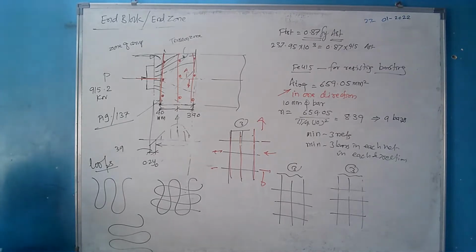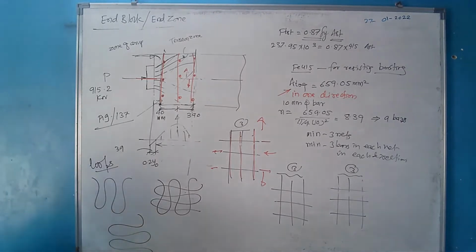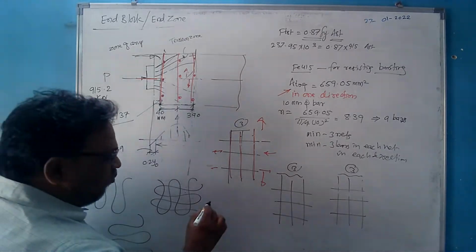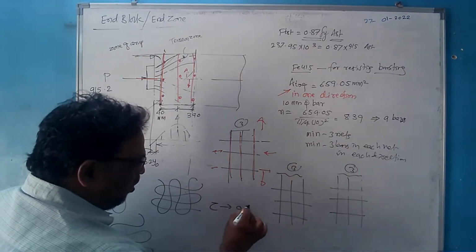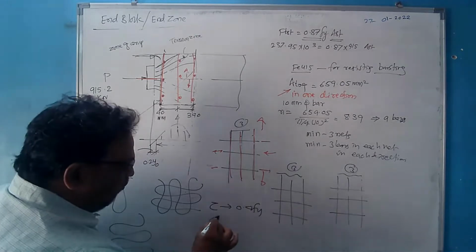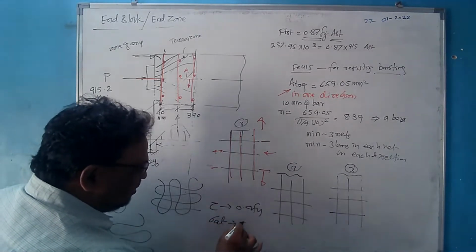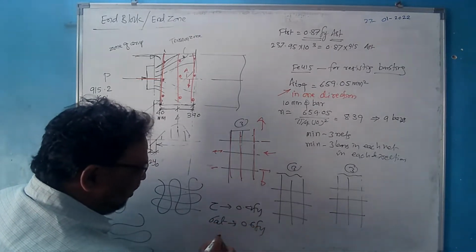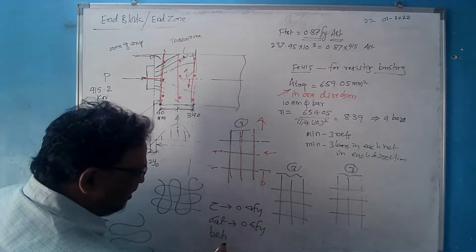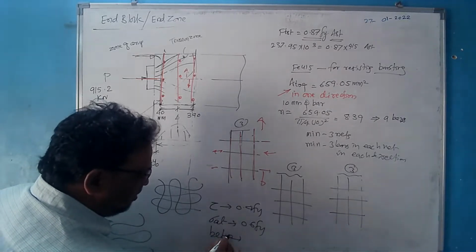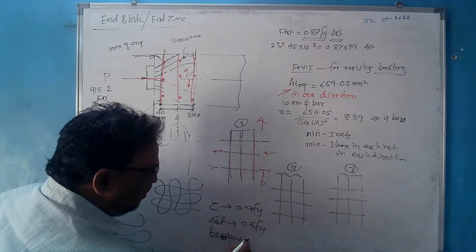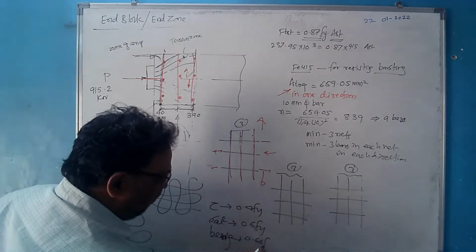कैसे है कि there are different methods of design. पहले हम बहुत सारा पार्ट वर्किंग स्ट्रेस से करते थे. तो वर्किंग स्ट्रेस में क्या रहता था? For shear stresses consider 0.4 times of Fy, for axial tension consider 0.6 times of Fy, for bending consider the permissible values of stresses as 0.66 times of Fy.